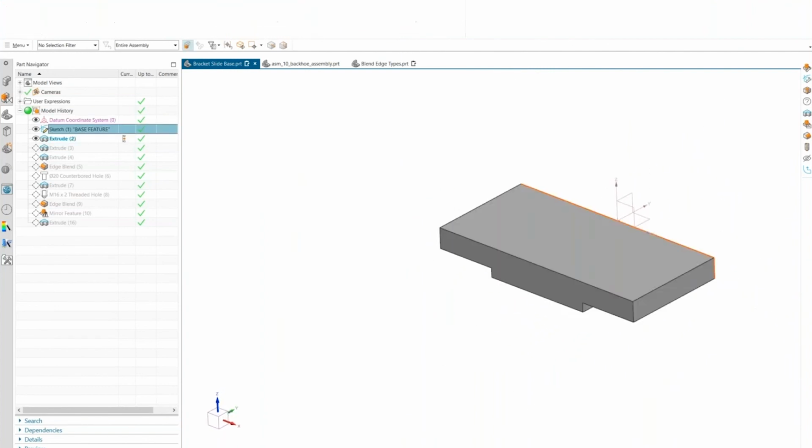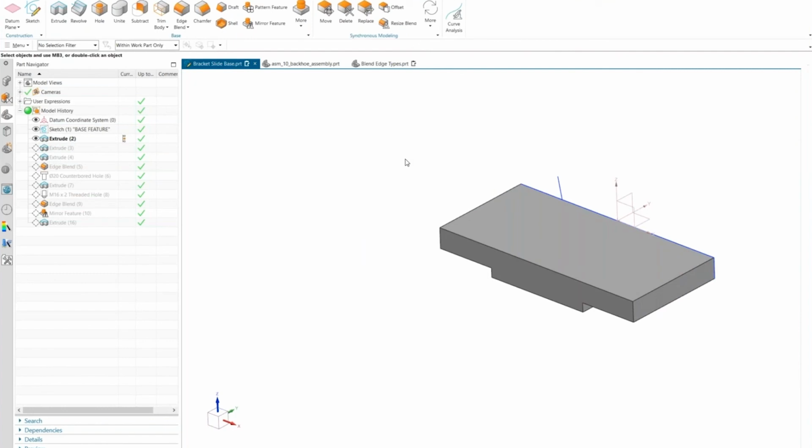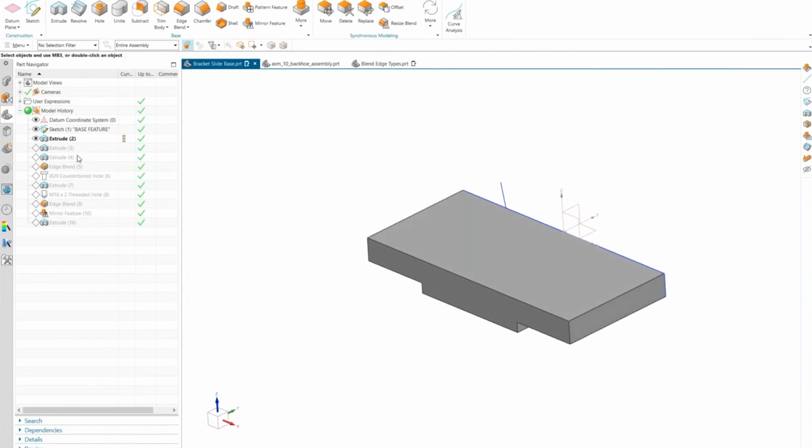And if I go into my sketch that I'm using and throw that line back in, NX ignores that now. Maybe it's just a reference curve. Who cares? You're not telling me to use that as part of the extruded feature. So something to keep in mind as you're working with various tools, selection intent becomes a really important aspect of the design process.